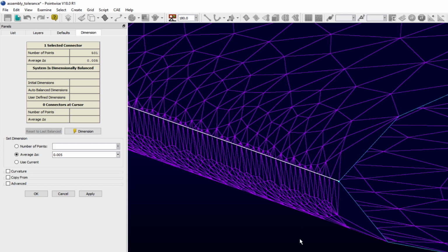The vertices of triangles are being projected to the nearest underlying surface, but unfortunately, that surface is 0.01 inches away, and so the triangles become stretched along the lower quilt. The problem is aggravated further at the quilt boundaries along the root and tip of the wing section, and the mesh along the upper quilt along the leading edge is particularly interesting.